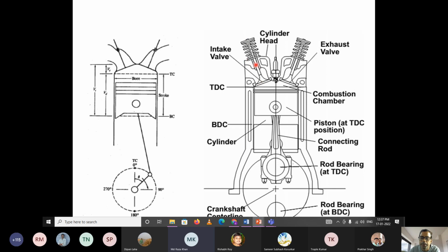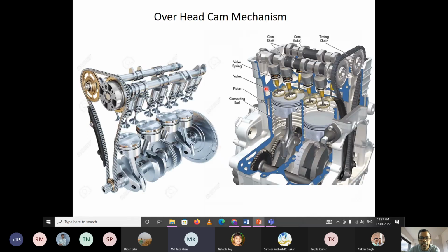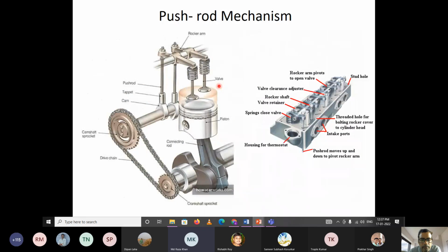This is part of the spring, and this part is connected to the intake manifold. Right now it is closed. When the rocker arm pushes, the valve will come in and move inside the combustion chamber, and the opening area is going to be clear, and whatever the intake, fresh air will come into the combustion chamber. Clear here now? Yes, sir.